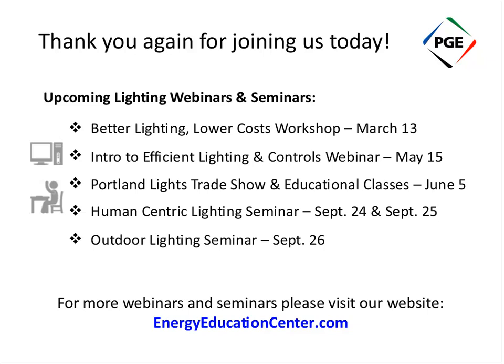So you can get LEDs that have a CRI of 93 or better, which is really very good. But there are a lot of LEDs that have CRI closer to 70, and those would not be a good choice if you really want to replace a halogen light source. It's not going to be good enough. You're not going to be happy with that. But there are LED lamps with a high CRI that I think do very well.